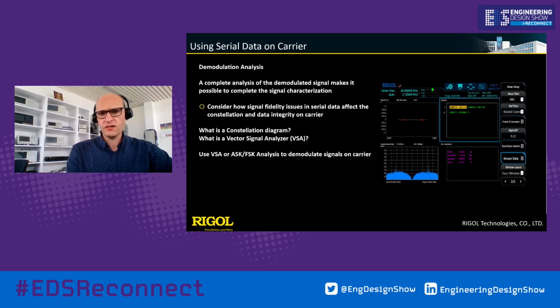What we're using as well for such analysis is the vector signal analyzer. The vector signal analyzer can be used to demodulate a digitally modulated carrier. Here we have different tools. For example, we have the constellation diagram on the one side. We have the capability to demodulate the symbols. We also have the capability to display the error summary, and we see the frequency spectrum. We also have possibilities to display other views, for example, the eye diagram of the I or of the Q, or do burst analysis and a time view.